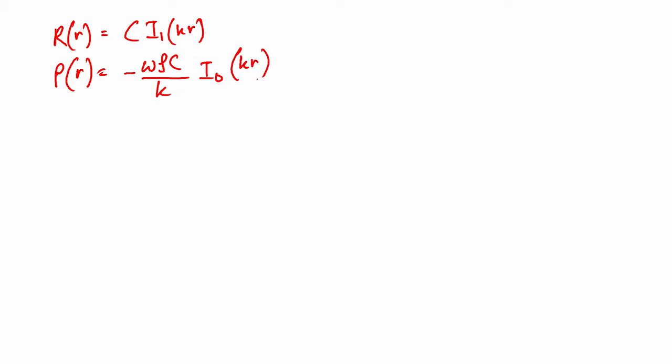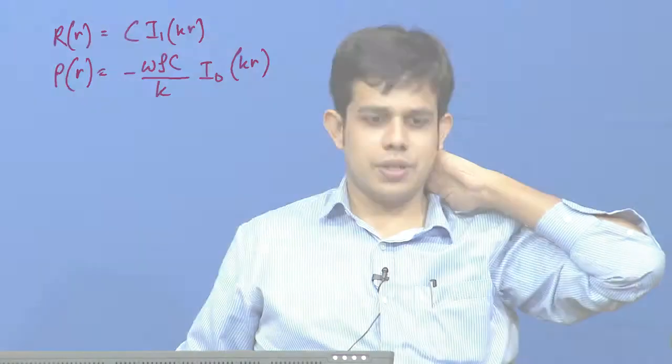So, we have the amplitude of the surface fluctuations and the amplitude of the pressure fluctuations in the radial direction as Bessel functions of the first kind. But these constants are there, so to eliminate the constants we need the appropriate boundary conditions.